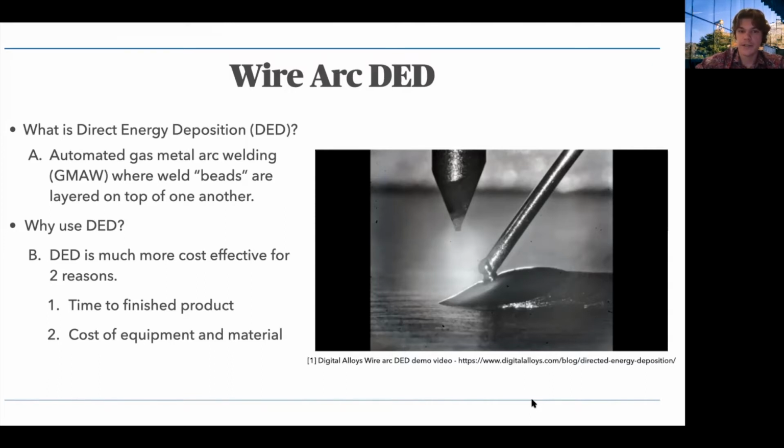An automated GMAW, or in our application, we were using a MIG welder, has the arc coming straight from the filler rod, which is acting as the electrode, which is that more perpendicular looking piece in the video. And the electrode will produce the arc that will melt the filler rod, but if they're all in the same piece, it's like having a 3D printer nozzle, and it can follow its track layer by layer.